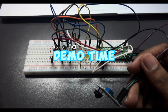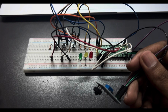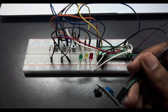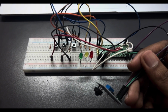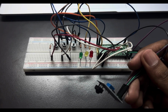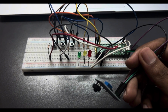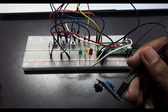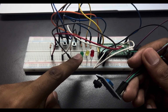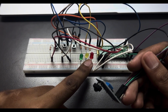Here I would like to present my AutoGate prototype. As you can see, I use a microcontroller PyPico and 3 LEDs, red, yellow, green, with 330 ohm resistors, and 3 push button switches with 10k resistors, and an IR sensor for the obstacle detection. The opening is for the green and closing is red, and obstacle detection for the yellow.